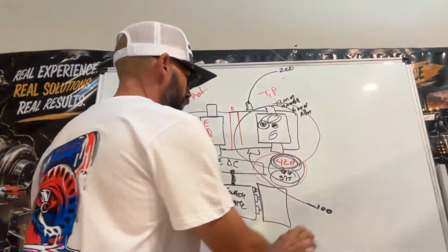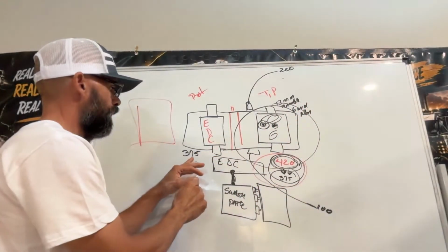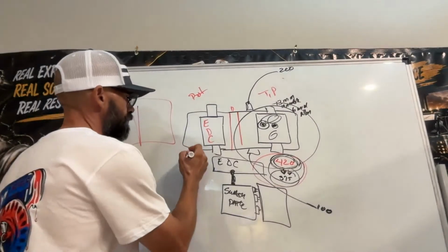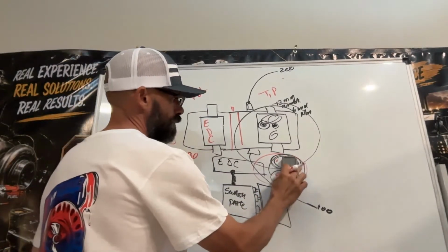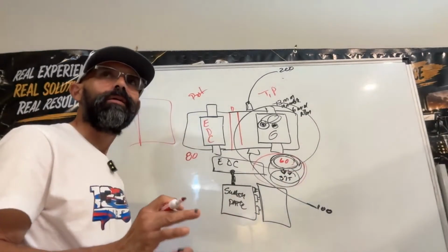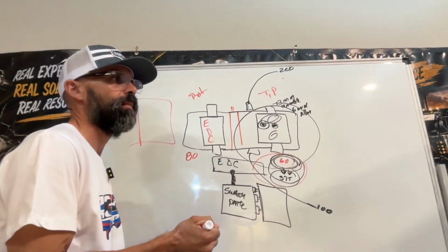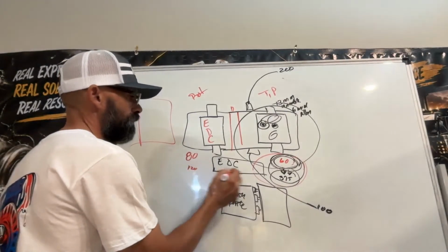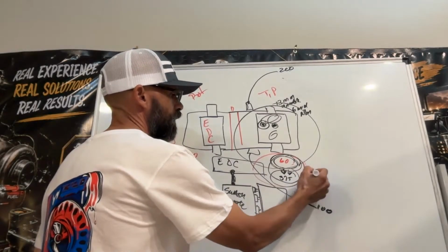Now, what happens if all of a sudden you lose pressure? Well, not lose pressure. Let's say that this one now is giving you 80 psi, and this one is giving you, I don't know, 60. Right? A high idle. Well, that's concerning. And you go to the relief valve, you try to crank it in, tighten it, bury that set screw, and you see that it jumps from 80 maybe to 120, and this one from 60 maybe to 115, right?